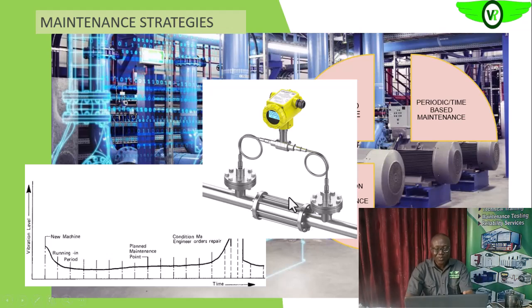So like in this case now, once delta P is increasing, what would that tell you? That the filter is due for change out. Now assume that maybe PM says 2 months, and you are now seeing that delta P has increased beyond what is tolerable, and we are yet to get to that 2 months. What will you do? Should we wait till that 2 months? Of course not. If we wait till that 2 months, it can cause further damage to our pump, because that increased delta P will reduce the pressure at the suction of our pump, can cause cavitation, and will also affect what will come out from the pump discharge and affect other processes downstream. So we will not wait. We will change it so that our operations will become normal again.